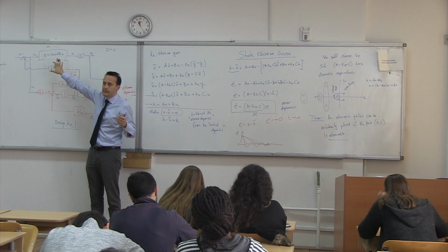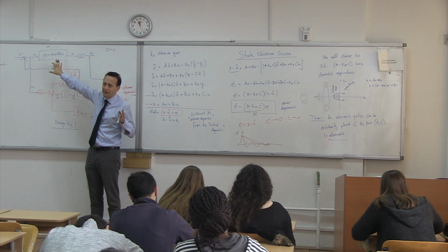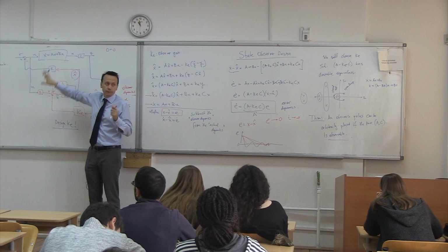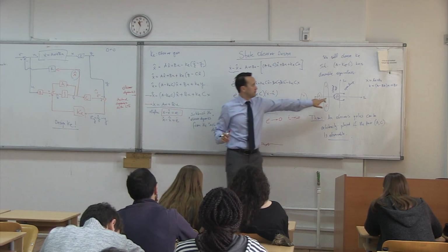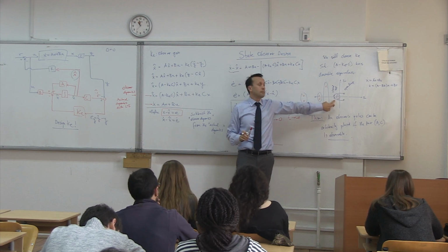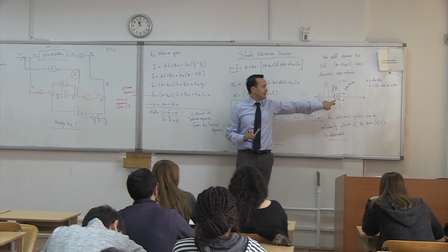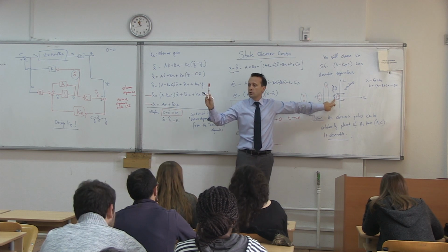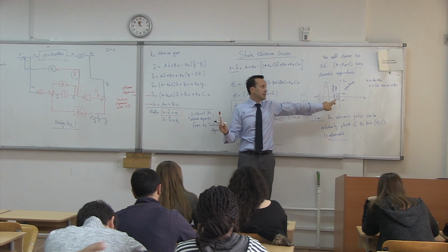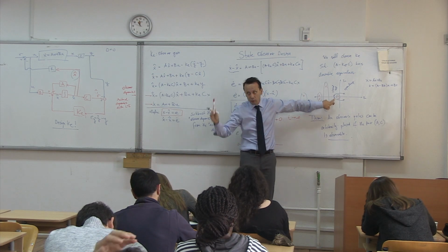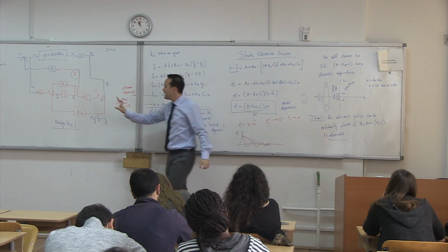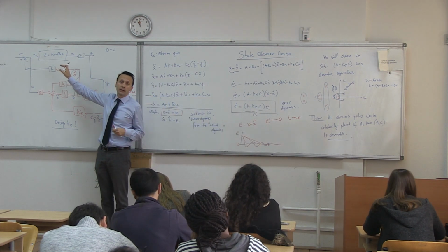So that's a trick. If the requirement of the closed loop is to converge at a certain speed, then the observer must converge before that so that this can in fact converge at a certain time. Otherwise you will have a closed loop system that wants to converge but can't, because the x hats are feeding back incorrectly.